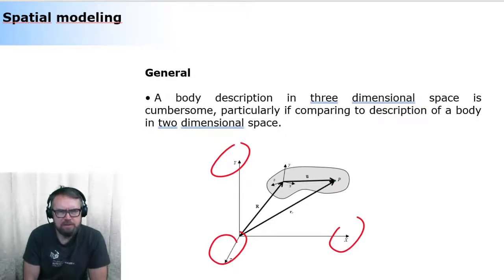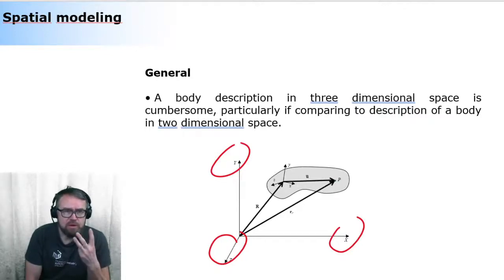There are several reasons for that. First of all, if you're describing your rotations using 3 parameters, which is the first obvious selection, you have 3 different ways using 3 parameters. Whenever using 3 parameters, you have a problem. And the problem is singularity, or not being capable to describe rotations as independent rotations.